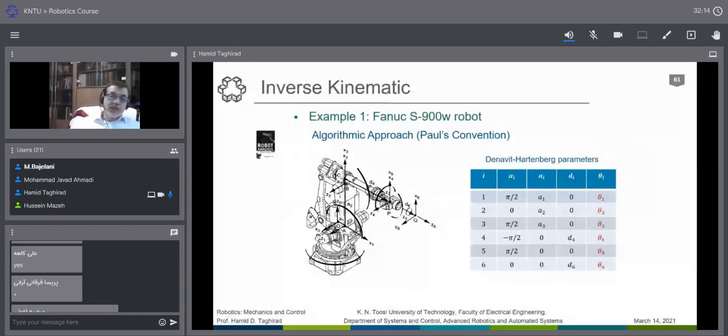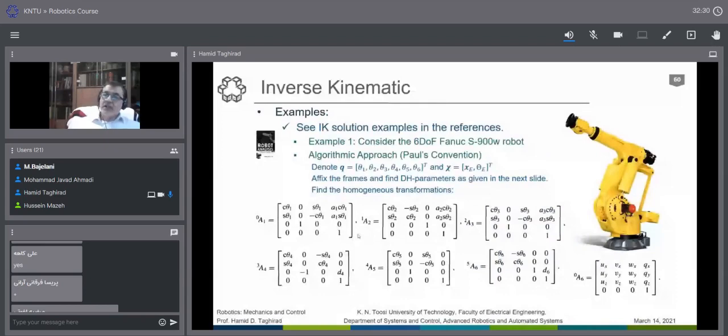But in terms of kinematic structure, we have this frame assignment here, and we can basically find the Denavit-Hartenberg homogeneous transformation as theta 1, theta 2, theta 3, very simple with this, and theta 4, 5, and 6 here. We have some D4 and D6 here, as you see. We have D4 and D6 as some links, and A1, A2, A3 as the first three link lengths.